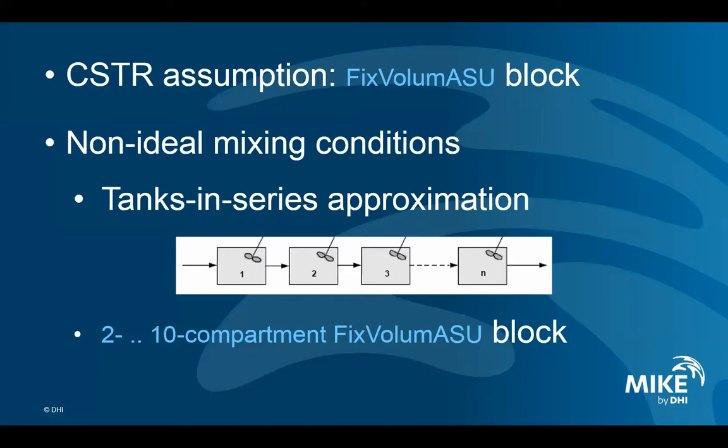But the question is now, how can I choose how many compartments are appropriate for a given situation? And one way is clearly to conduct a tracer test on my real scale tank, to spike a certain amount of non-reactive soluble substance, the tracer, and to measure the recovery of that same substance at the outlet of the tank. Then to model the test and compare the measured data set with the output of the simulation. And this is what I would like to demonstrate in the video.